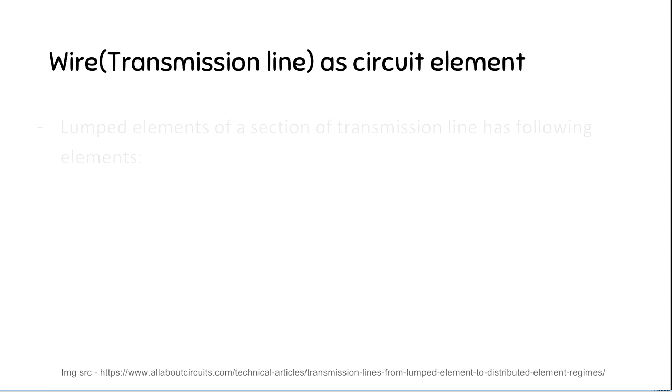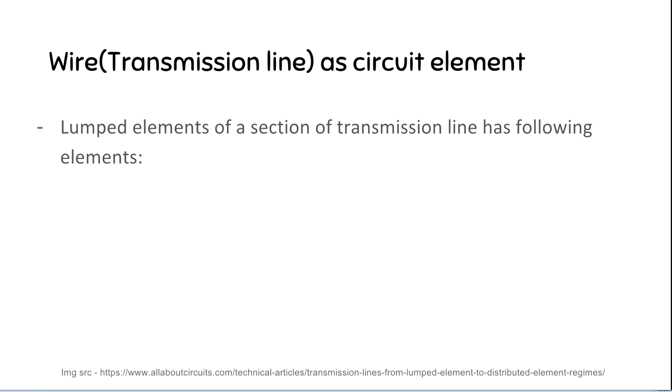So, to send an electric signal, we need two wires. Since two metal conductors placed side by side constitute a capacitor, each section of our transmission line has some capacitance. And since each loop of wire is by definition an inductor, each section of our line has some inductance. Also, as the wire has some inherent resistance, each section of our line has some resistance.